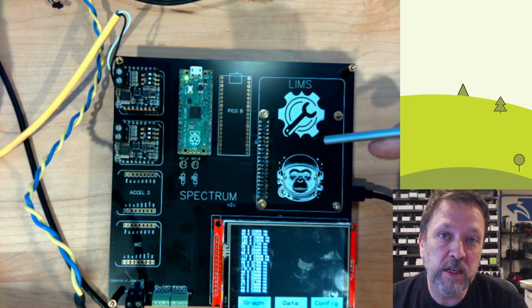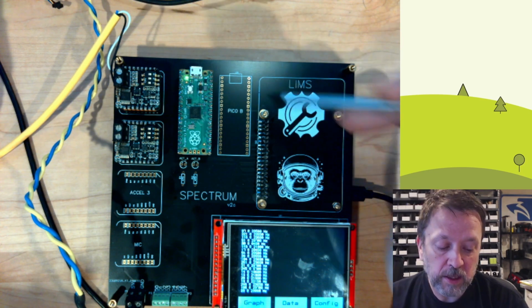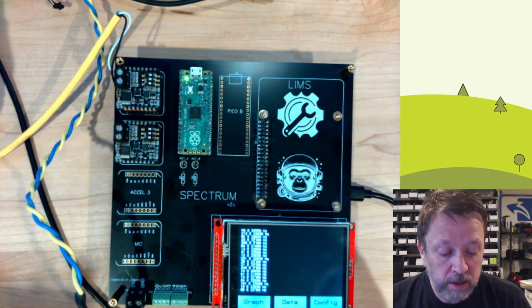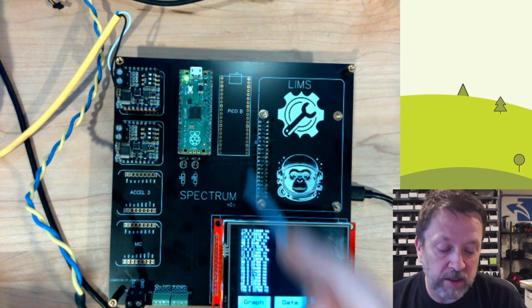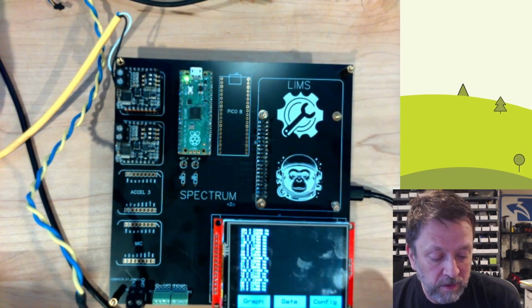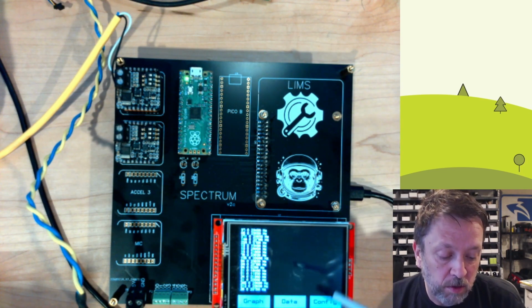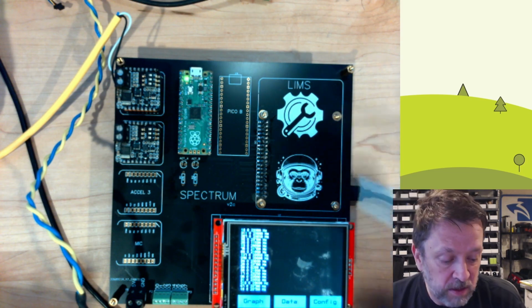It's simply listening to 2 different serial ports for the FFT data, and it then stores it and both presents it and will, in the future, have it in a WebSocket. I haven't done that development yet. I still have a fair bit of hardware to do. But you can see what I end up with is this display, and this is an SPI display, so we're not using the HDMI capability of the device.